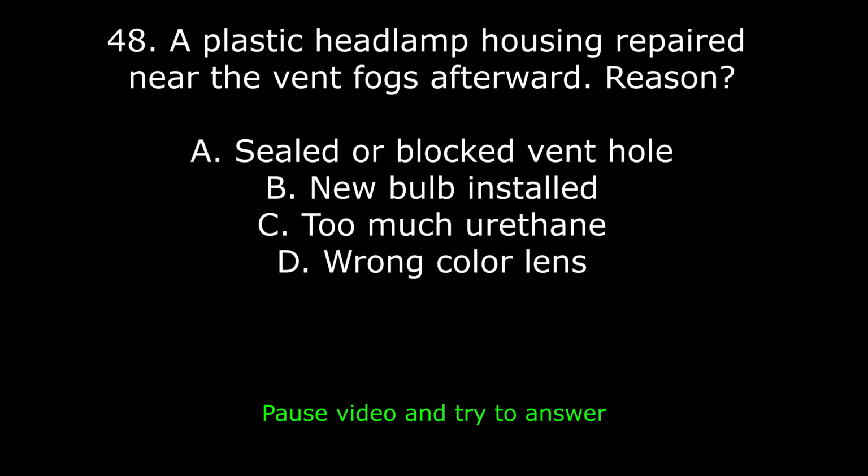48. A plastic headlamp housing repaired near the vent fogs afterward. Reason: A. Sealed or blocked vent hole. B. New bulb installed. C. Too much urethane. D. Wrong color lens. Answer: A. Sealed or blocked vent hole. Explanation: trapped moisture condenses without ventilation.